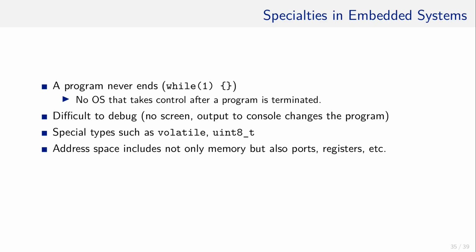Often, the entire memory is addressable and accessible. That not only includes the RAM in the processor, but also the CPU registers or registers controlling the pins, for example. So the developer can exactly determine when and how the pin has power or not by writing values to specific addresses. That means that one address might alter the state of the pins, while another points to the value stored in the RAM. More about how that works in the next lecture, which will be very exciting.